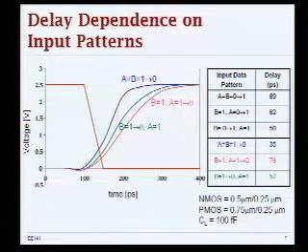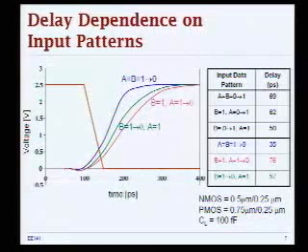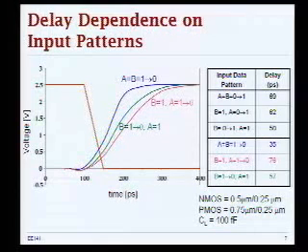Because when both of your A and B are switching, during the initial period of your transition, both of these PMOS transistors on top are also turned on, right? And you'll be fighting them a little bit for a short period of time until you fully turn on your NMOS devices. And from that point in time, you have to discharge 2 capacitances: your load capacitance and also your intrinsic capacitance.